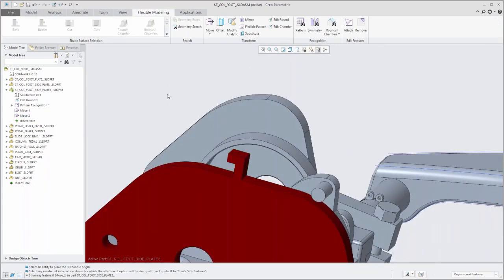So this is flexible modeling in the traditional sense, right? We call up some geometry. It doesn't really matter where it is. It could be Pro-E geometry. And from that standpoint, it's actually pretty good for doing design reviews. If your manager or customer says, hey, why don't you move this over here or change this? And you're thinking, oh, by the way, I built this part, if I parametrically make that change, it might work, it might not. I might have to go into redefine. Here you can just grab geometry, like I said, anybody's geometry, including our own, and make those changes non-parametrically, and have a chance of getting some real-time feedback and not worrying about parent-child relationships and relations and all that kind of stuff.